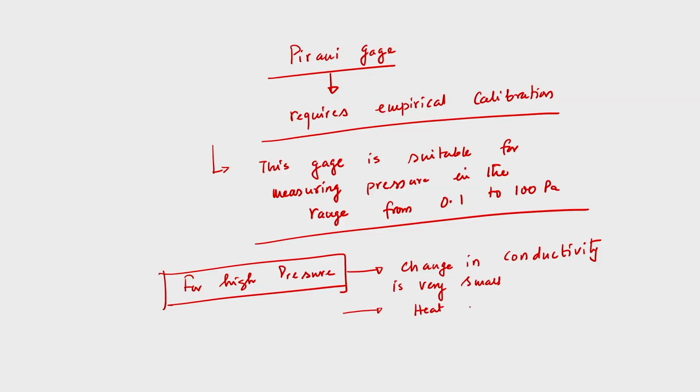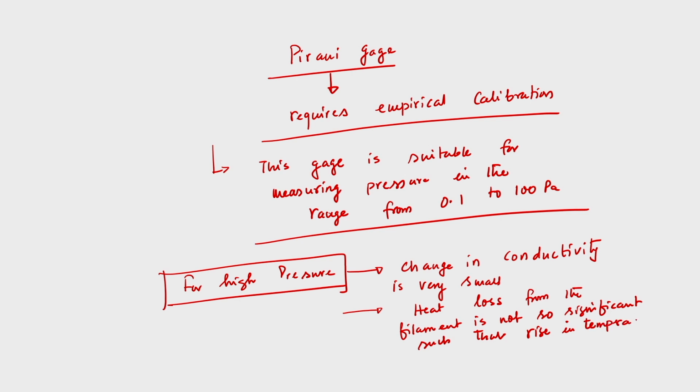If the change in conductivity is very small, then the heat loss from the filament is not so significant, such that the rise in temperature of the filament is not appreciable.